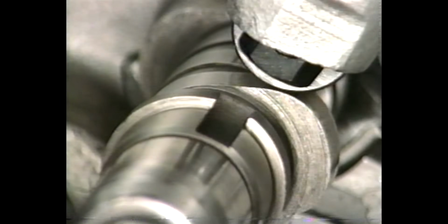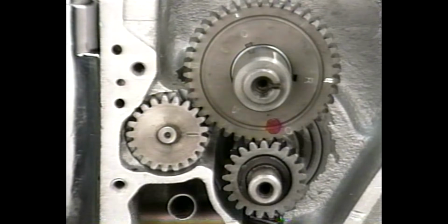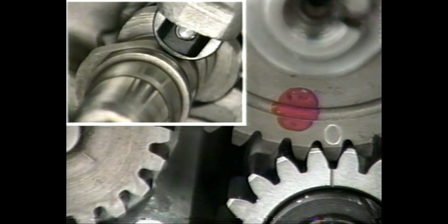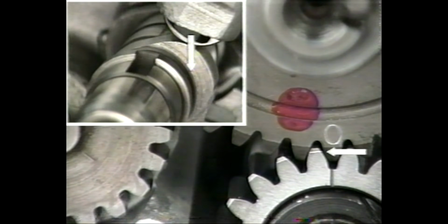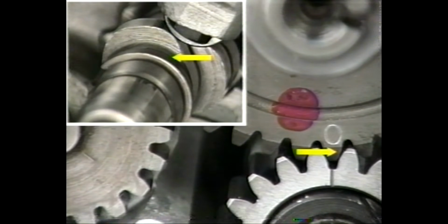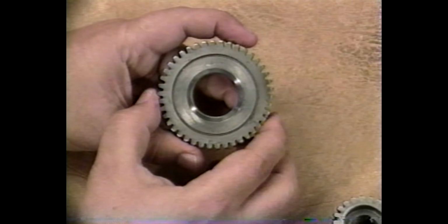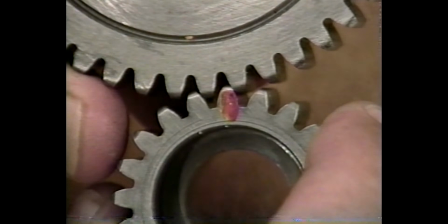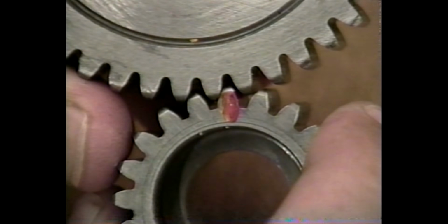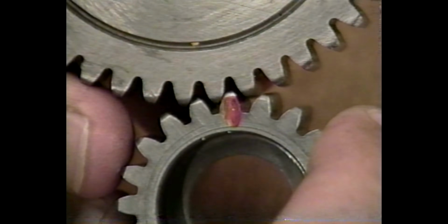As our lifters pass over their respective cam lobes' maximum lift points during rotation, the direction of force exerted by the valve springs via the lifters suddenly changes from the front side to the rear side of the cam lobe. This causes the cam drive gear to ever so slightly kick back during its rotation. As a result of this slight kickback, the cam drive gear teeth will rock back and forth against the pinion gear teeth. This movement is called backlash.